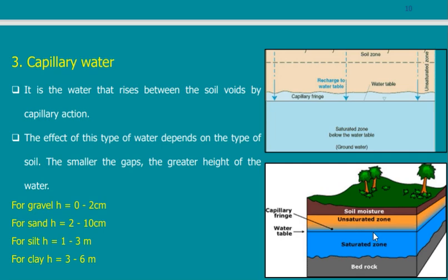You remove the soil. There is no capillary, there are no voids for the water to rise. It's just air. You now have only water. How is water going to rise beneath the level of water if there is air? So obviously it will return to the water table level.